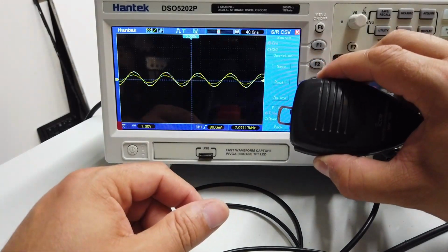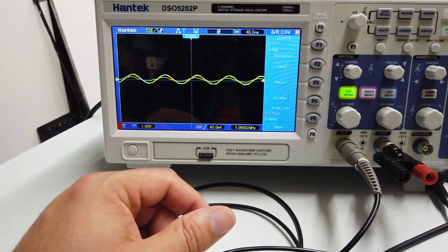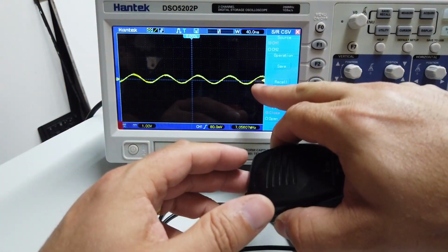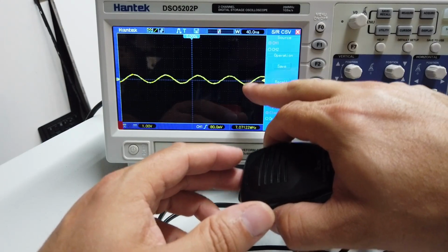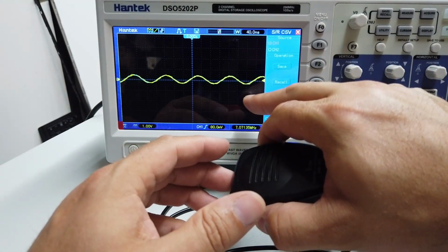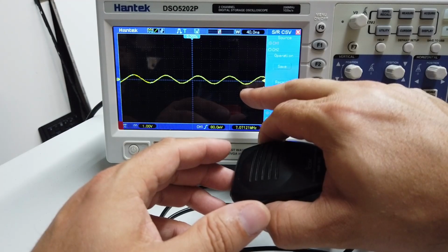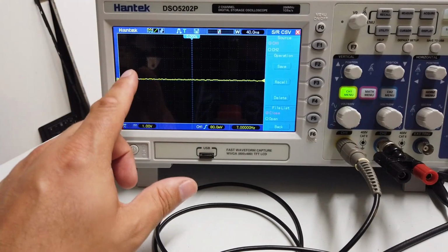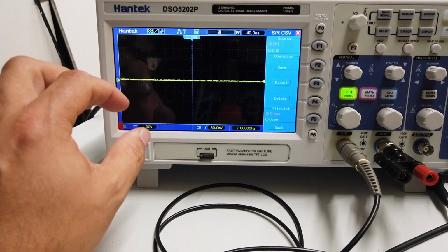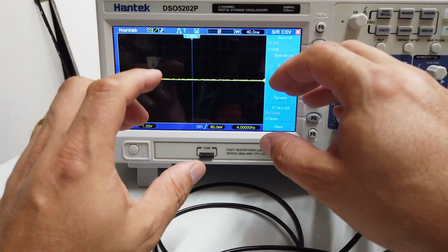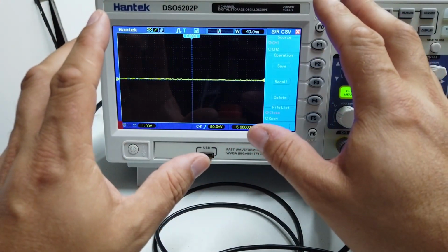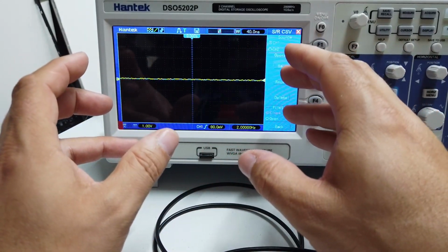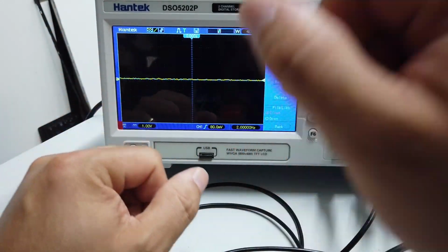So you can see here then, in AM mode, when I'm transmitting and speaking into the microphone, there is always a carrier wave, and that carrier wave modulates ever so slightly. So when you're transmitting in AM mode, ultimately you're always transmitting a carrier wave. So it's not the most efficient mode of operation because you're always transmitting a carrier wave. Whereas with a single sideband mode of transmission, you're not transmitting any carrier waves.